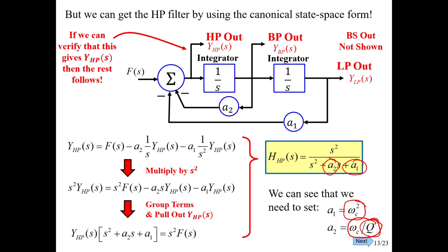The larger it gets, the closer the poles are to the J omega axis, and the higher any peaks are in the filter, whether it's a resonant low pass or high pass, which is the case here, or a band pass filter. The bandwidth gets very narrow relative to the center frequency. But that's the idea.